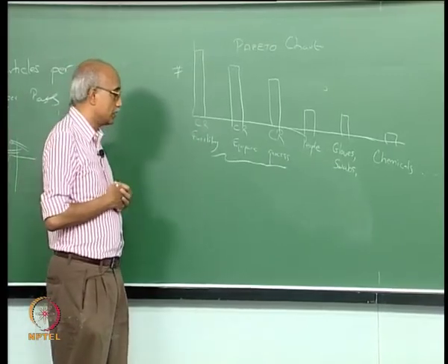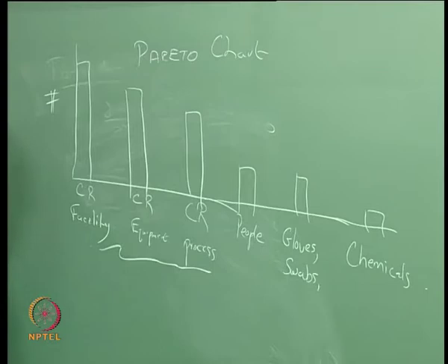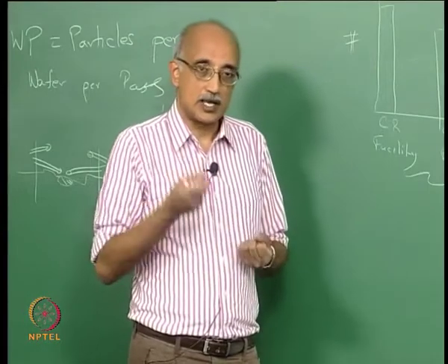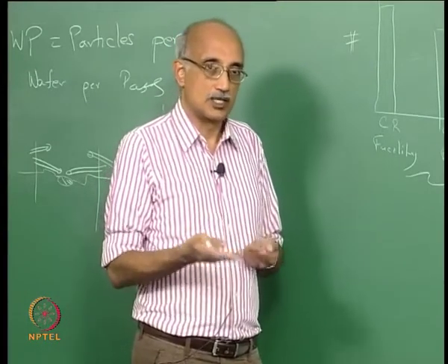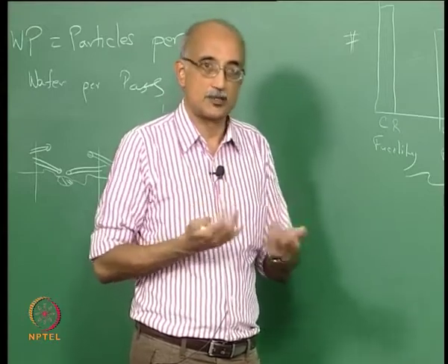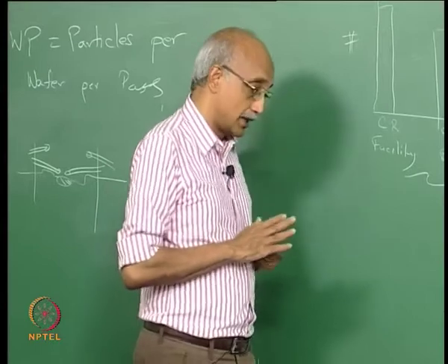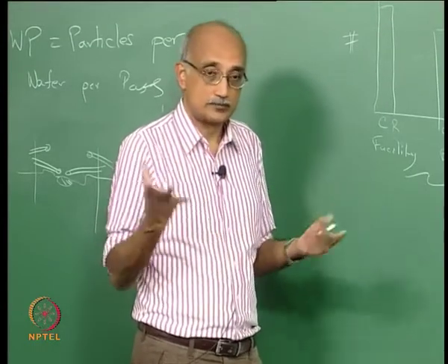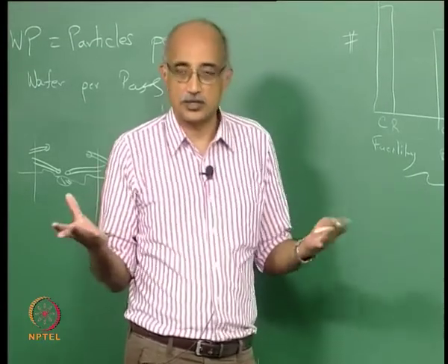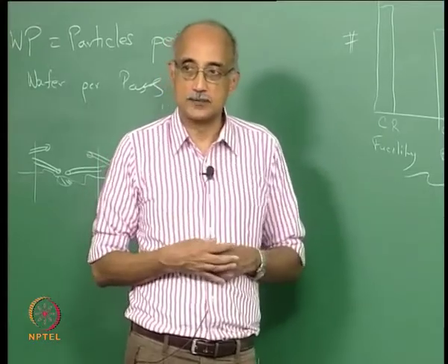On the other hand, if I find that the equipment is contributing particles, then I would want to look at, is the equipment properly designed? Is it made of the right material? Does it have the right surface finish? Are some surfaces too rough and contributing particles by abrasion mechanisms? Or is it that there are some oils that are spewing out as aerosols and getting counted as particles?